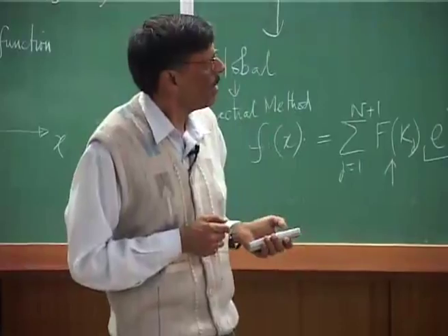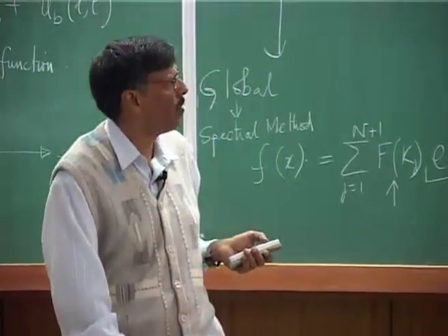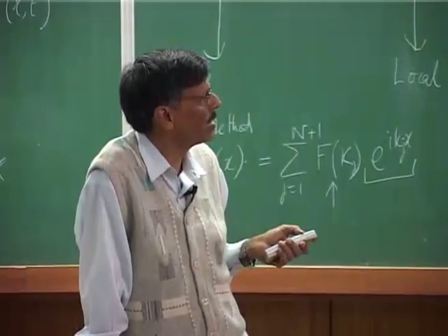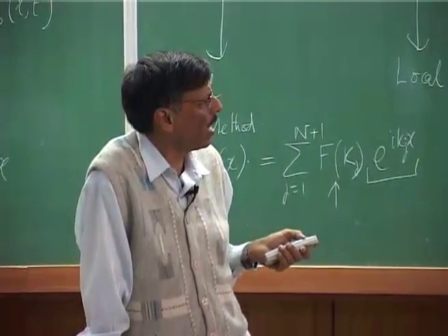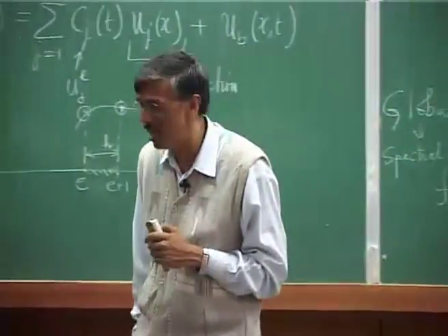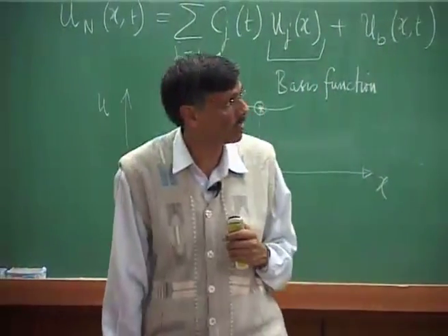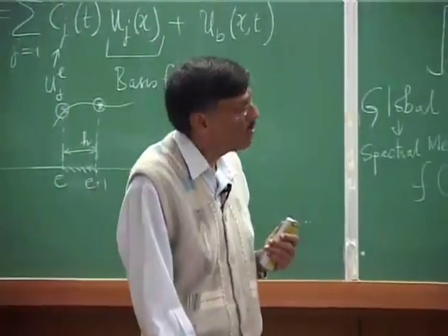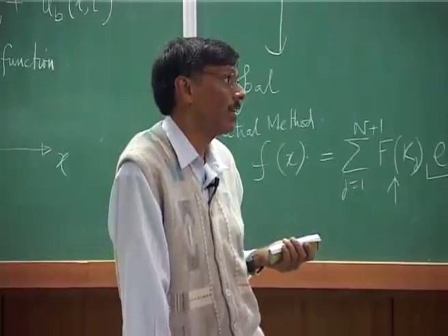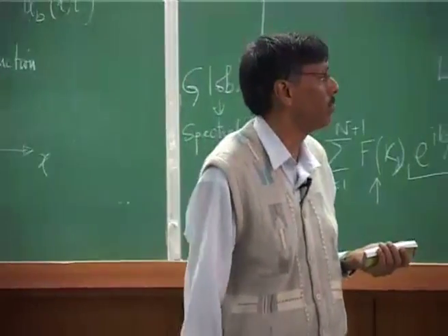So, whenever we adopt this weak form, then we are satisfying the differential equation in approximate form, and if there are any derivative boundary conditions, those are satisfied. That is the way we choose those phi j of E, etc. Okay. Whereas, if you have some Dirichlet type of boundary condition at the end of the elements, they have to be specifically satisfied by the approximate solution.